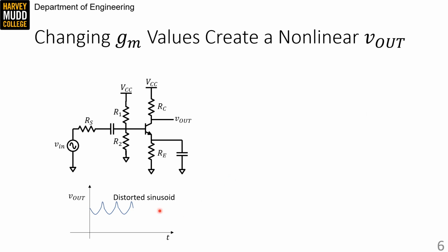Here the output sine wave looks different on top than on bottom, appearing pinched and probably not reaching the full 0 to peak value that you see at the bottom of the sine wave. We refer to any nonlinear behavior in an amplifier's output as distortion, and common emitter amplifiers are very distortion prone for even modest output swings, so you don't need to clip your transistor by entering another region of operation to see nonlinearity.